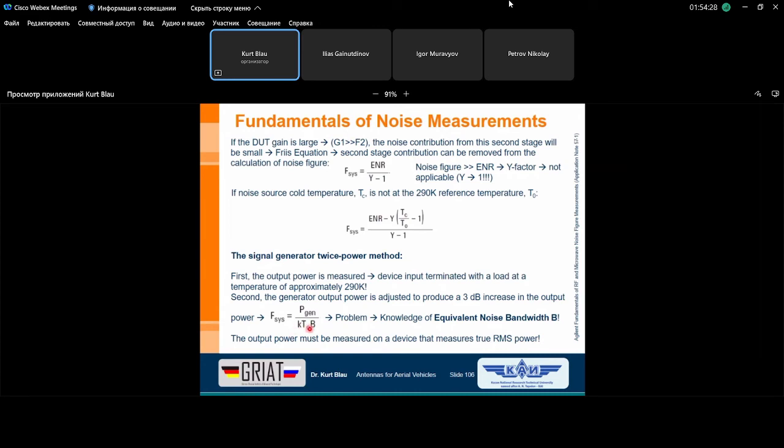But again, the noise figure itself can be much higher than the value we know from low noise amplifiers as the input stage of a receiver. In our case, we also speak of a noise figure of 30 dB, or in this case, F is in the order of 1000.